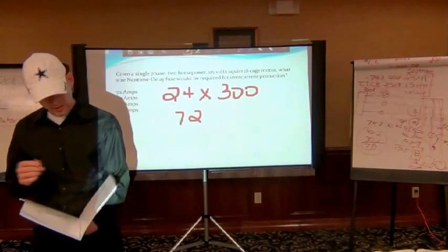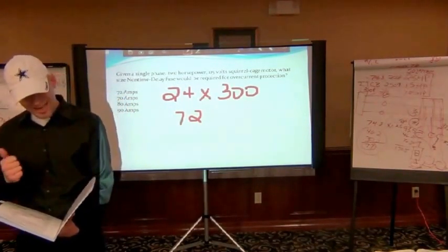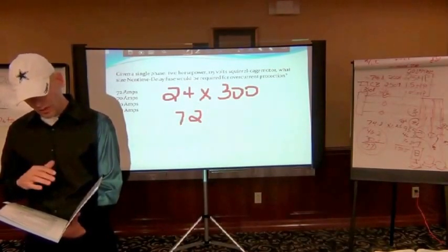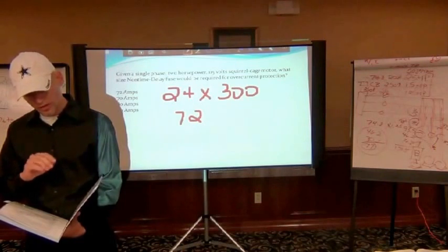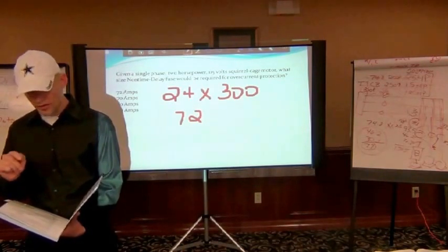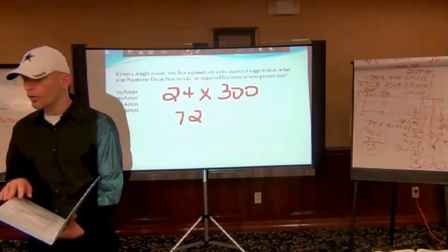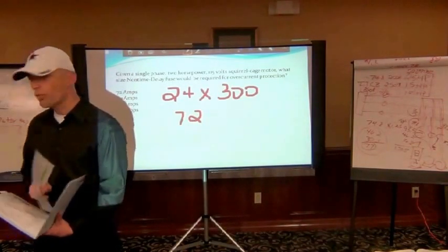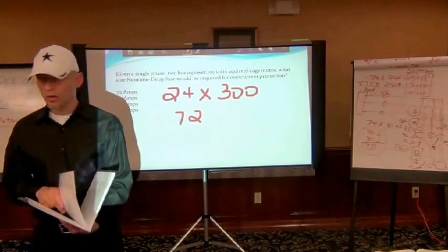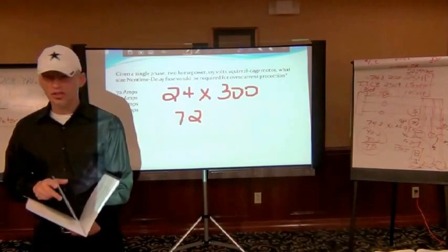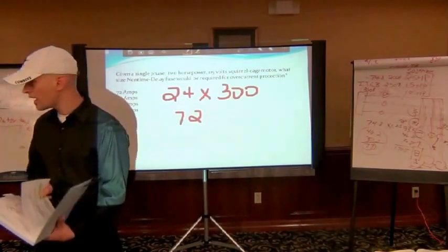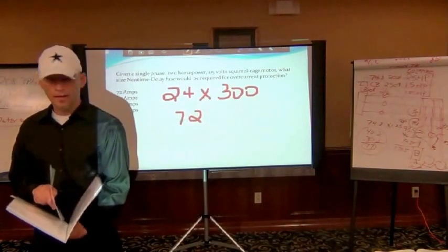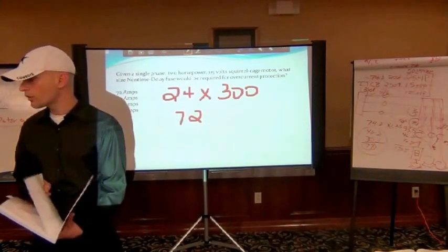The next one you had was what size THHN wire is needed to supply a 120 volt, 2 horsepower single-phase motor with a 45 degrees Celsius and a service factor of 1.10. What page would we be on for that one? What were they asking for? They're looking for wire, right? Does the service factor have anything to do with wire sizing? No. Absolutely not. They put that in there just so that you'd be on the wrong page.